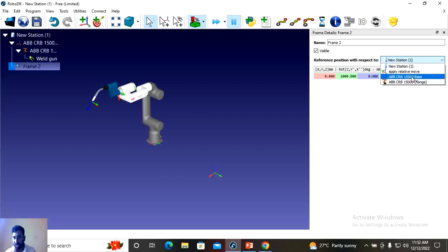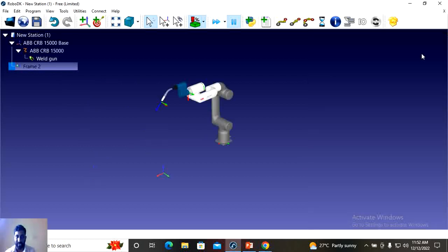Okay, so just for example, for a base, I will give this one x, y, and z axis. The x is 1000 and y is 0. Okay, then see the change in the reference frame. If you know these values, you can change this reference frame according to your need in front of this robot. Okay, then here this is target.